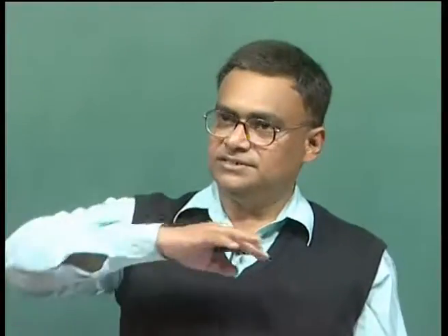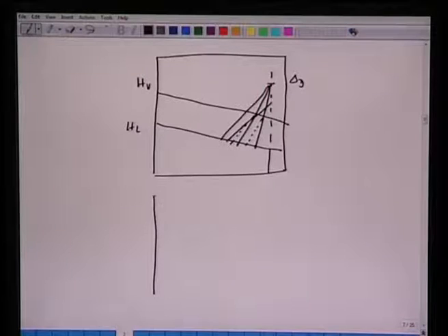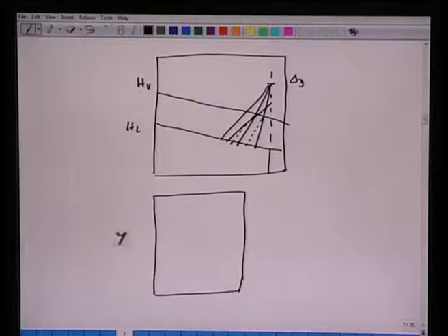Now also, if you recall in our previous lecture, we said that we can have ideal solutions or non-ideal solutions. Very often when we have ideal solutions, the shape of this TXY diagram is concave downward. If you have non-ideal solutions, what we are talking about essentially is azeotropic mixtures. In that case, if you look at the XY diagram, we have a different type of XY diagram.